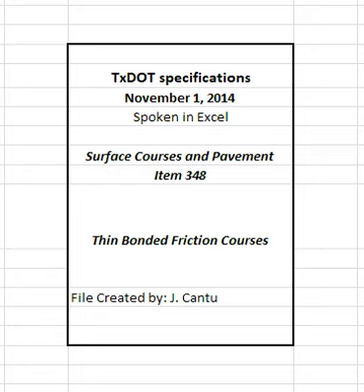4.7 Placement operations. Collect haul tickets from each load of mixture delivered to the project and provide the department's copy to the engineer approximately every hour, or as directed. Use a handheld thermal camera or infrared thermometer, when a thermal imaging system is not used, to measure and record the internal temperature of the mixture as discharged from the truck or material transfer device, MTD, before or as the mix enters the paver and an approximate station number or GPS coordinates on each ticket.